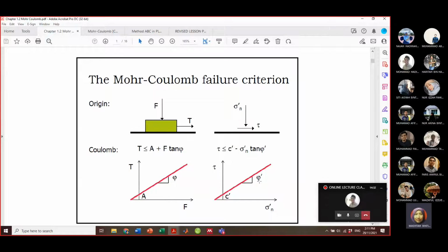And the shear failure represents the mode of the sample by the end of the stages, for example, from the consolidation stage to the shearing stage, as well as the effect of the pore water pressure. And from the experiment, the strength parameters of the soil are derived, such as c and phi. And if you remember, the Mohr-Coulomb will tell you the Mohr circle as well as the failure equation, which is tau equals c plus sigma n tan phi. So how this is derived comes from the Mohr circle plus Coulomb failure criterion.